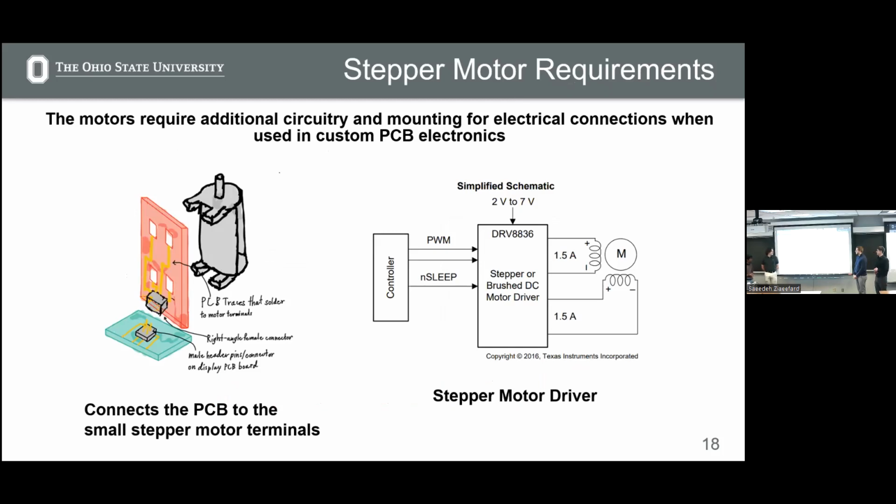So the last few slides discussed the software and high-level solutions needed to interface with the stepper motors. But if we want to use them in our design, we will also need to make hardware changes as well. One issue with the stepper motors is their very small footprint. They have tiny terminals that make it difficult to electrically and physically connect them to a larger device. But the picture on the left shows one solution that I devised to get past this issue.